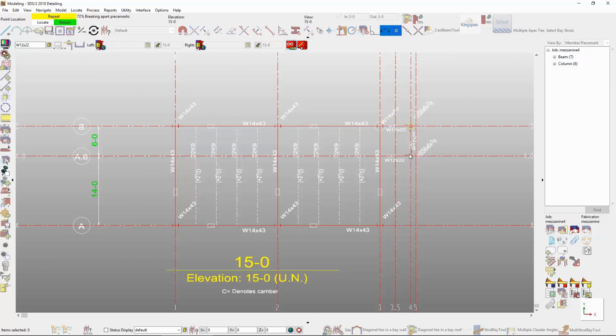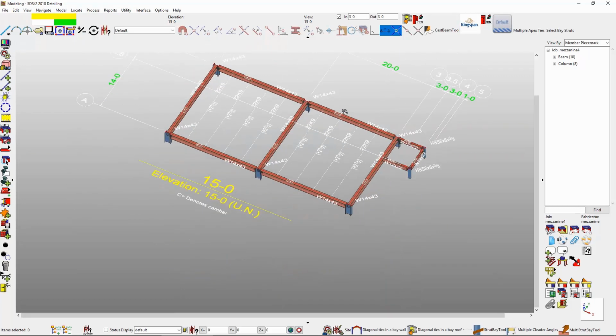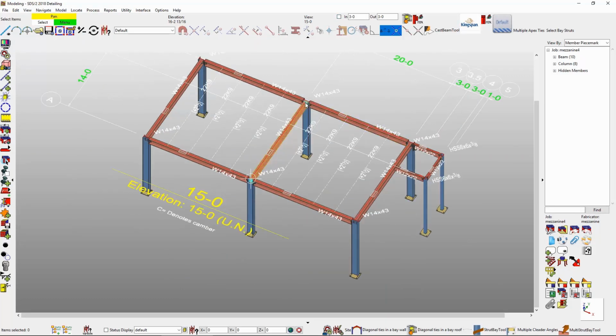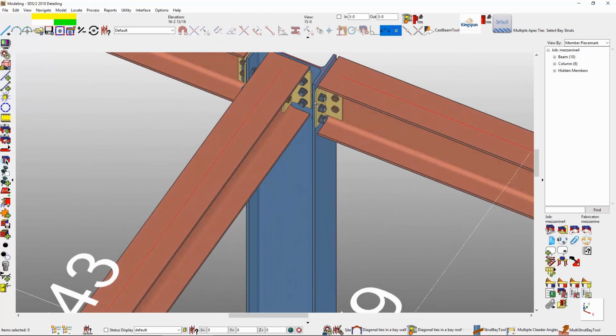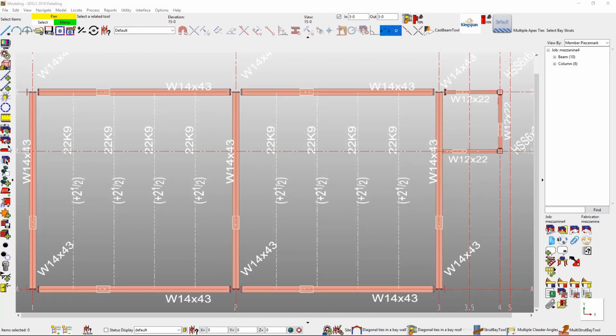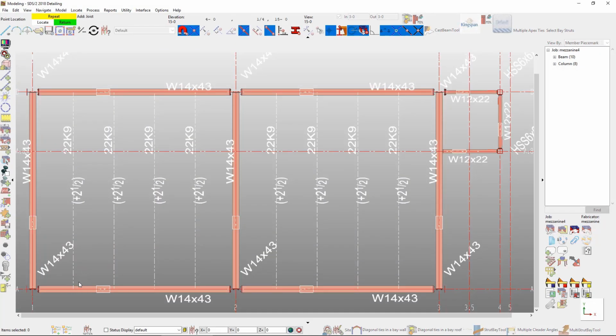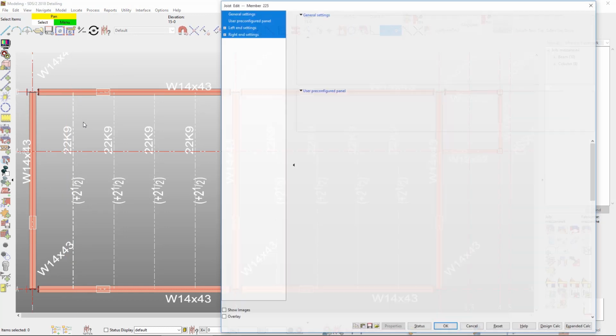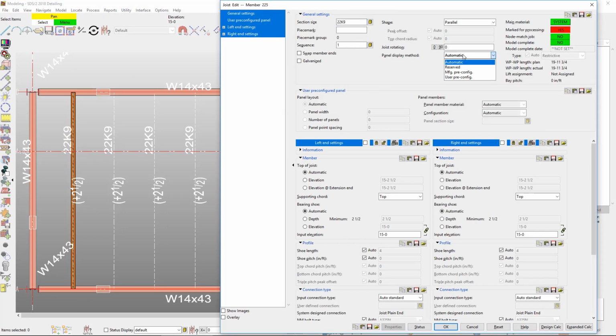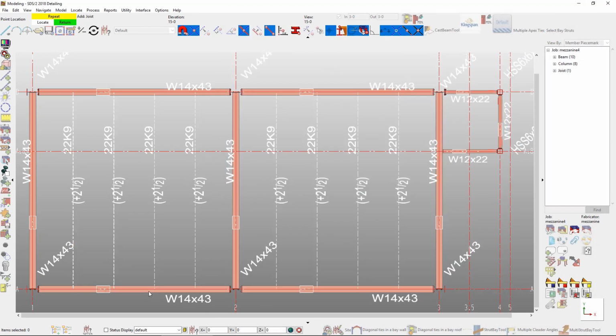Once you have added all of the structural members, the system will automatically design the connections. We use a code-based connection design routine that looks for both perpendicular and opposing members to make sure that your connections will fit in the field. Whether these are beams, columns, bracing, or joists, SDS2 has these connection checks that you can then send to an engineer for verification and approval. This will make sure that they are meeting all your design requirements.